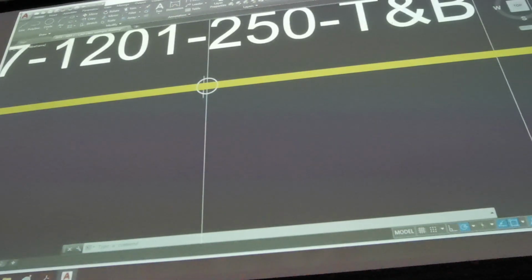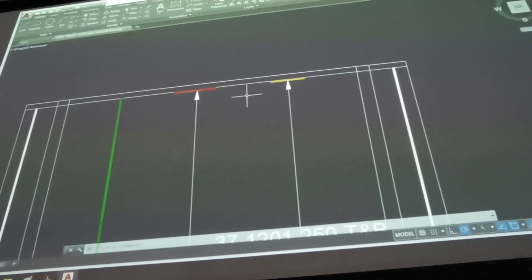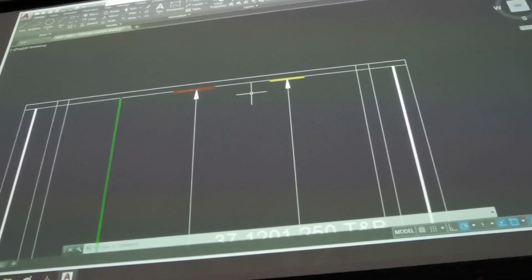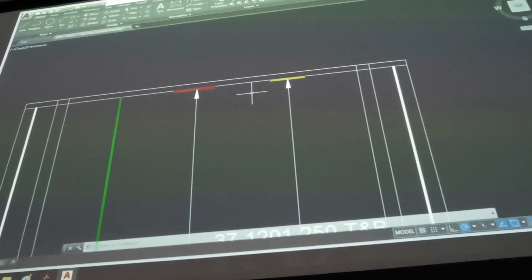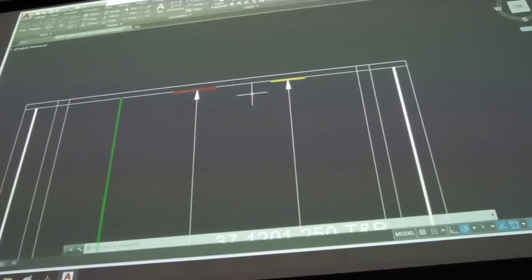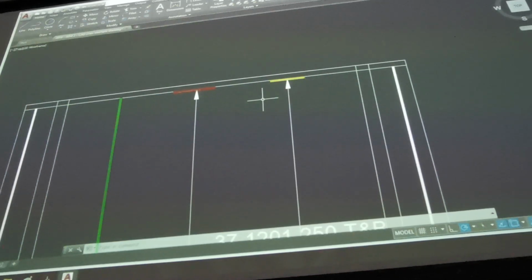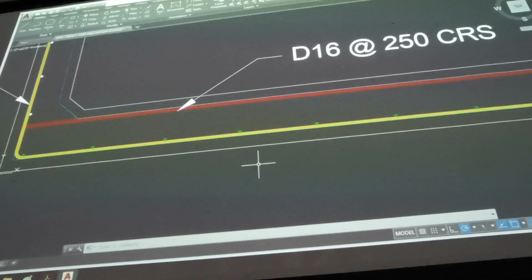Notice that these circles are about 2 times the diameter. I don't want emails saying, how big are the circles? 2 times the diameter. Right? And notice how I draw the delimiter bar. Now they're probably a little bit too big, but I would let you away with that, but no more. Probably about 3/4 of that size will be better. The delimiter bar represents the very end, the last bar, and it's only a very short little length, perhaps maybe 3 times the length of the arrow, something like that. The width of that bar has got to be equal to the diameter of the bar itself.